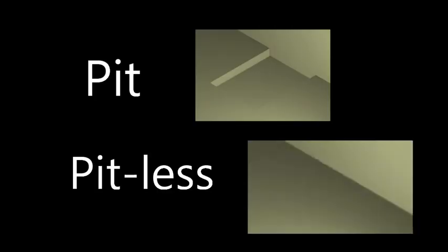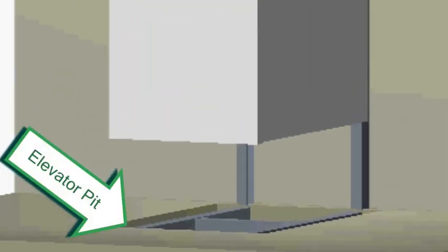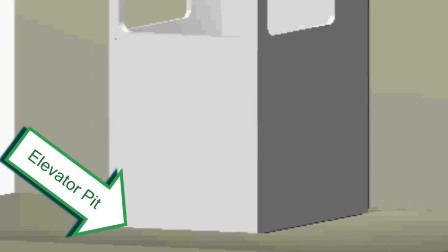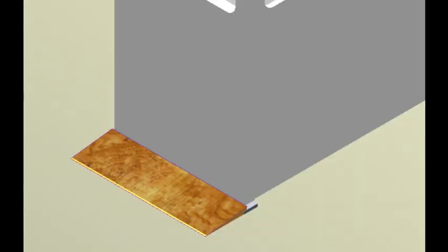This refers to the base preparation on the lowest floor to accept the elevator's platform and/or allow for some over-travel adjustment to assure the floor of the elevator can be adjusted even with the lower floor surface. Some elevators are considered pitless, where the front edge of the floor plate is beveled to make a ramp surface for ease into and out of the carriage. An alternative in some designs is to have a short 2-inch ramp built in front of the elevator.